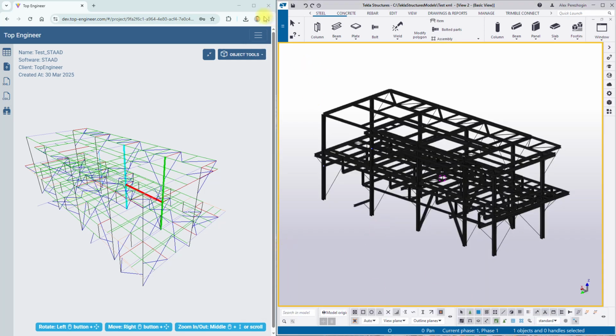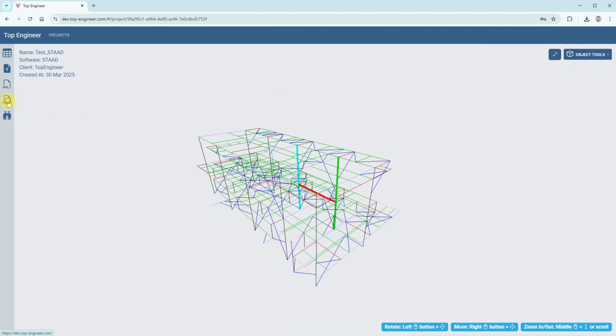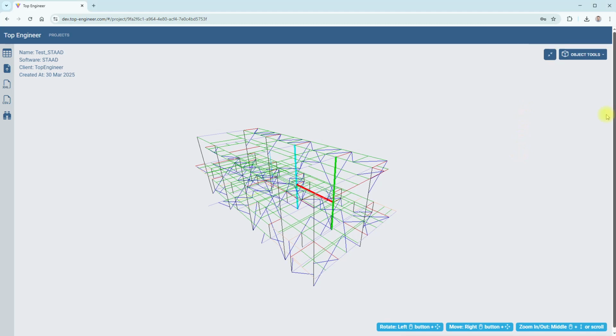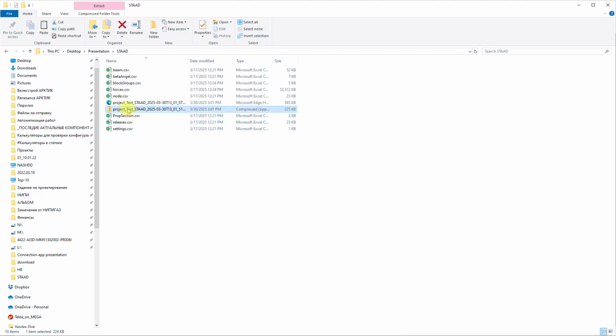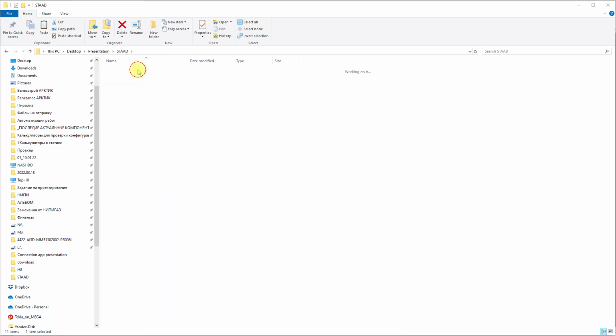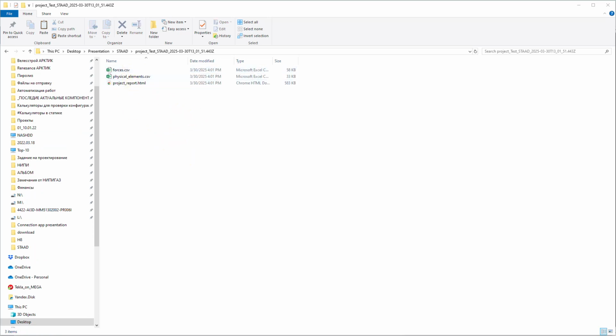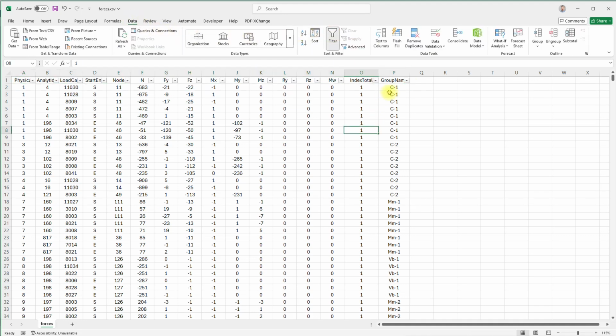Automated reports. The portal generates useful reports automatically to aid your design and documentation process. Excel spreadsheets. These contain structured data, including detailed element lists and critical forces. They are suitable for direct use or for further processing, like importing data into connection design software such as Idea Statica. PDF report. A comprehensive PDF report is also generated. It details the project structure, units used, the grouping nomenclature adopted, the theoretical basis applied, like sign conventions, and includes summary tables of elements and forces per group. This report is ideal for inclusion as part of your official calculation documentation.